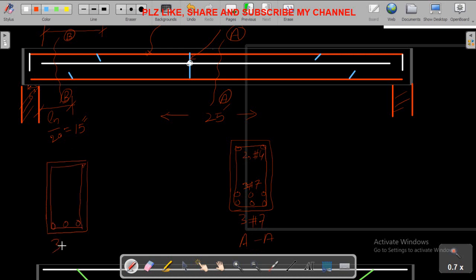At this point we have only 3 number 7 bar, because 3 number 7 bar are discontinued right here, and here we have 2 number 4 and 1 number 7, so 1 number 7 bar and 2 number 4 bar, and stirrup is number 3 at the rate of 12 inch center to center, right? And this is all about the curtailment of bars.